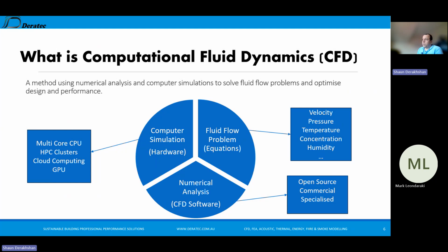Concentration, if we are talking about pollutants, such as in a car park, CO2, or a kitchen, is also important, in ppm. For example, recently I am doing an ice cream factory ammonia leakage. It's important to see the ppm and how the ammonia travels around the factory when a leakage happens, because of the safety and health problem for people or workers.